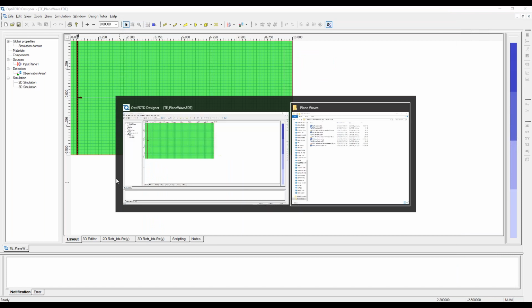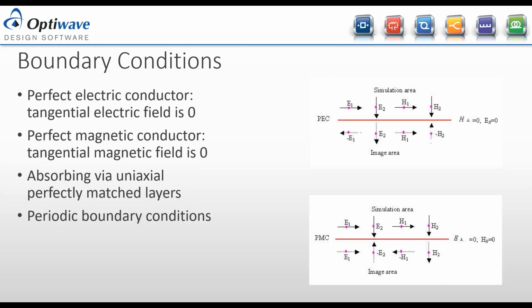So let's go back to the slides now. And yeah, so I showed sort of how to use those electric magnetic boundaries to set up a plane wave, right? However, if you know about wave theory or traveling wave theory, how reflections are created, you will know that if you send a plane wave at an electric conductor or a metal, the field will be totally reflected. If it's a perfect conductor, the field will be completely reflected, and none of it will penetrate into the metal.